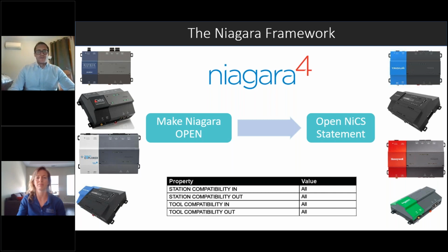What you'll find is that different manufacturers occasionally use different transceivers on their controllers, and a lot of times some of them will use different gauge wire as well that works best with their specific controller line. Like I said, that range can be anywhere from, I've seen, 16 to 22 gauge wire being used for BACnet MSTP communication, that twisted shielded pair.